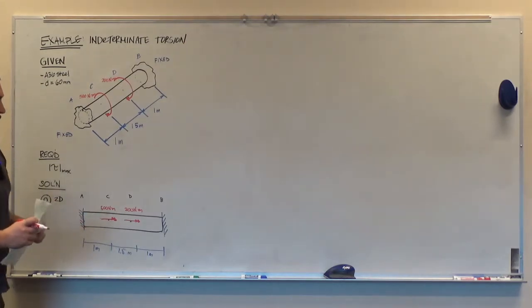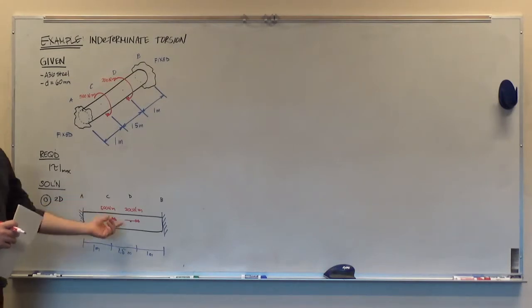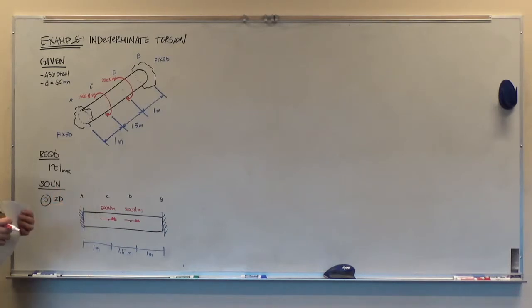The other option is to do the stiffness displacement method. And with that methodology, we would look at equilibrium first. We would figure out the relationship between all of the internal torques and the applied torques. We'd find that we don't have enough equations to solve for all the unknowns. We'd only have one equation. We'd have two unknowns in this situation.